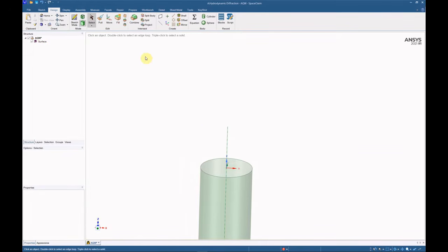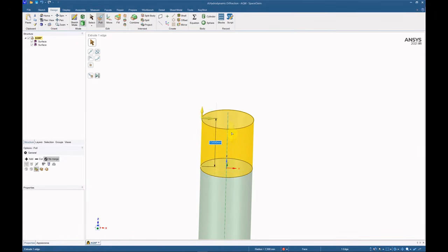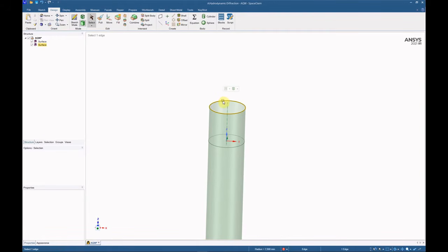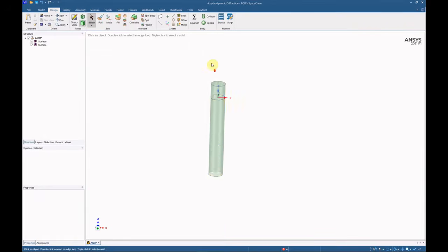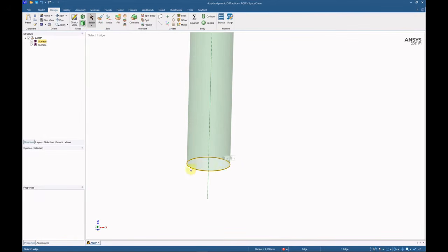Use the pull tool again, without merge, and extrude up with a hull freeboard of 15 meters. Use the fill tool to close the top with a surface. Verify that the hull bottom has a surface, because we need a closed volume for the submerged part.